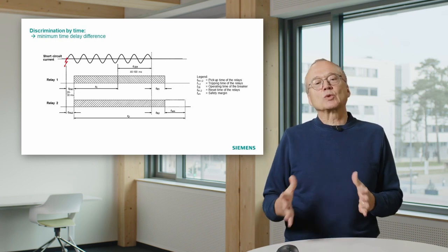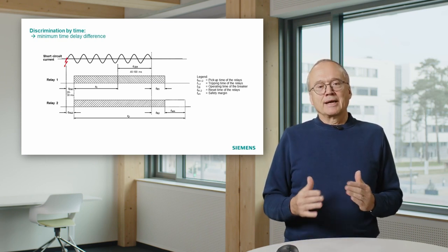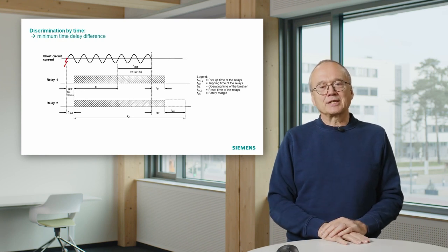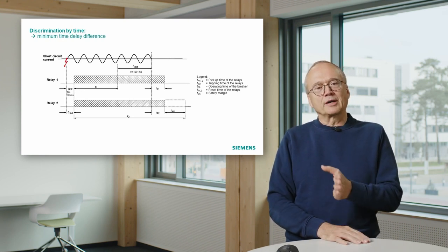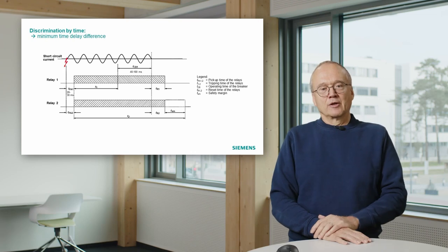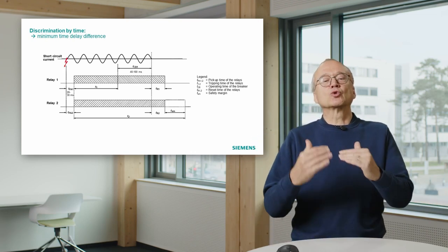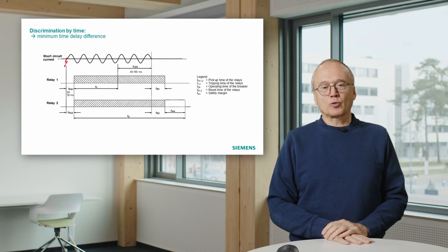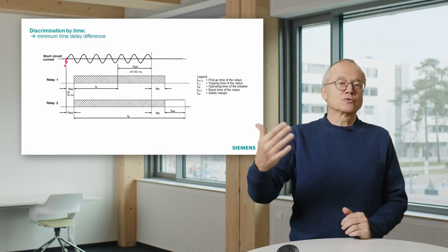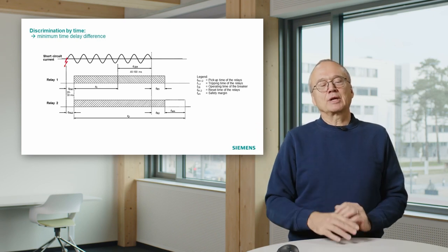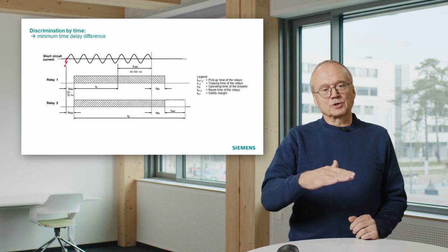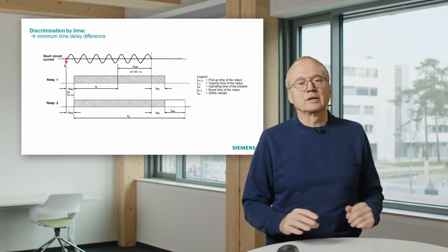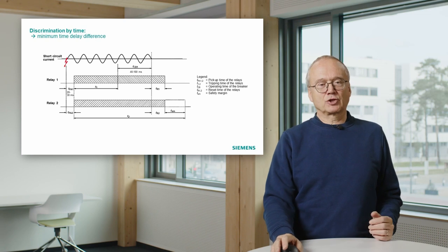And with this calculation, you end up in required differences of the timer setting in the range of 200, 250, 300 milliseconds. You should not go below that. In my example, I took 300 milliseconds. It's more the upper end. I think nowadays you can also go down to 250 or even to 200, but you must be pretty much careful then.